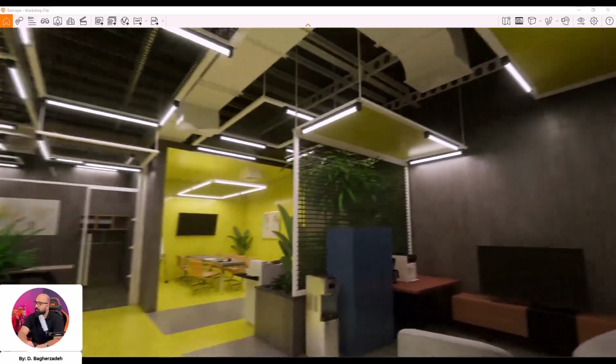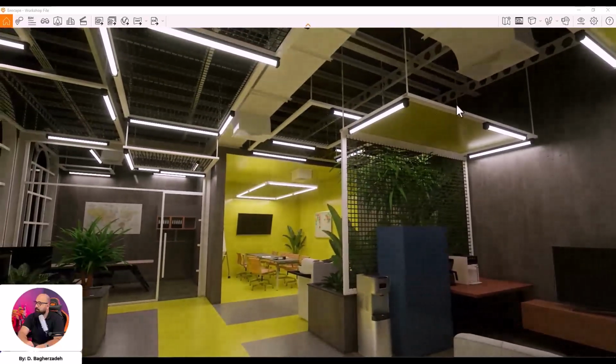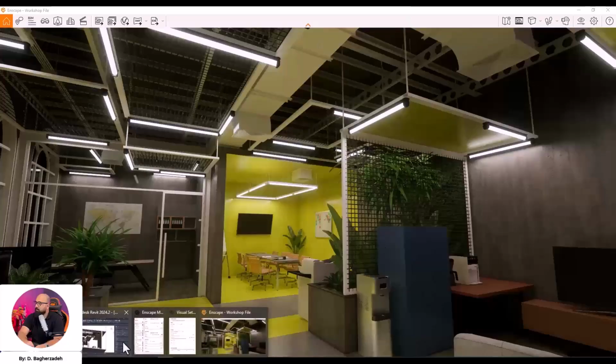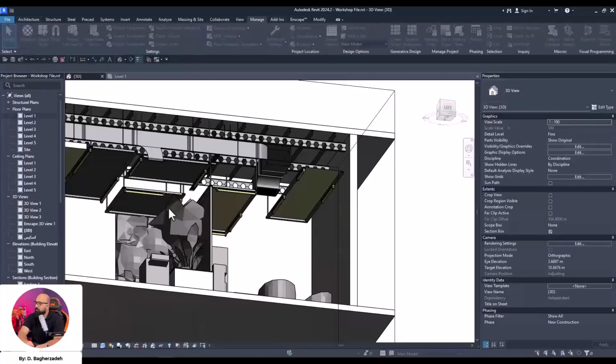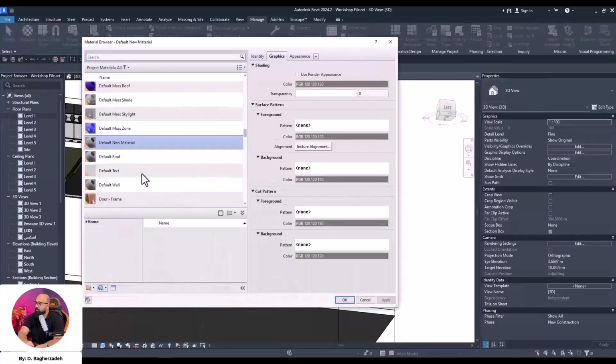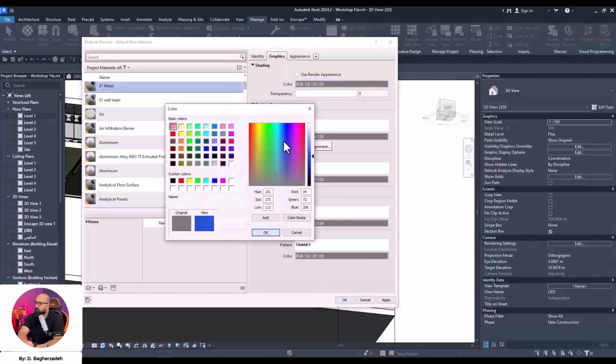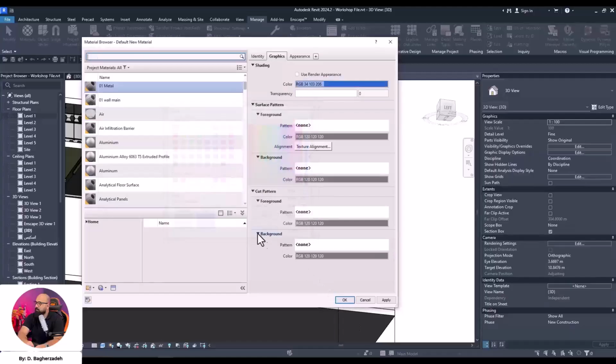Now, in the next step, we can work on a material for these frames that we have around our boxes. So, I'm going to go back here, then manage, then again, give me a new material, 01 metal. We can basically use this material for all the metallic items that we got. And by the way, these would be the secondary materials.